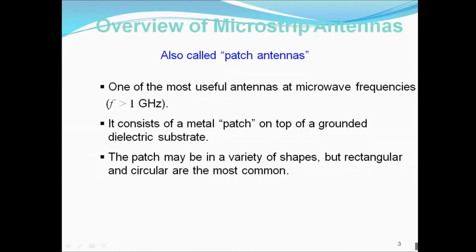Generally the microwave frequency range is above 1 gigahertz. The millimeter wave range is above 18 gigahertz to 110 gigahertz. Most colleges may have measurement devices for microstrip patch antennas only in the range below 14 gigahertz. But millimeter wave starts from 18 gigahertz.